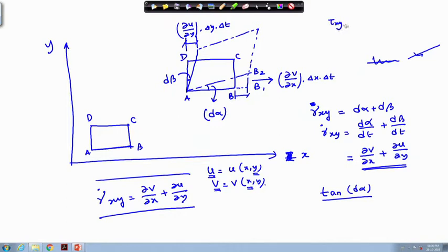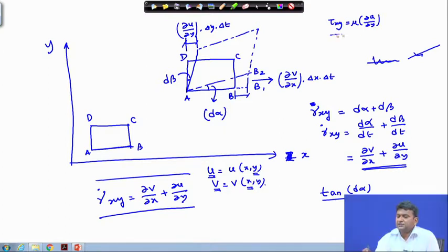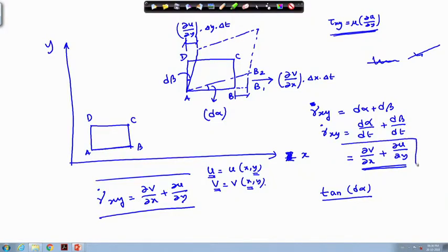But what is more important is to highlight to the students that what we write, tau y x is equal to mu del u del y, is actually a limiting expression of a Newtonian fluid for a 1D flow. We just argued in a more generic way, and that is exactly what I said when I started giving this lecture, that for a 2D flow field the angular deformation is not only limited to del u del y, but the angular deformation is del u del y plus del v del x.